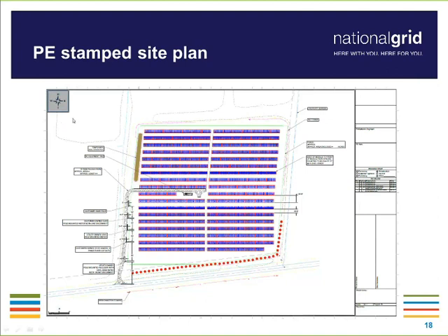And on this project, it would indicate to me that north was directly page north, or top of page. And then another good component is a scale. I like to talk to these items first because those are very critical to make sure we understand the orientation of the project and the scale relative to the drawing, in case we have any questions on physical arrangements or clearances or rights of way, space requirements that we would need or be concerned with.